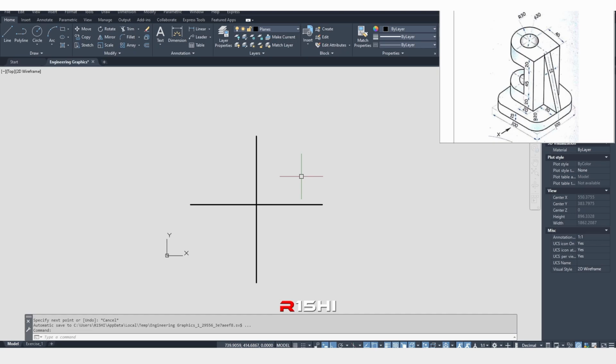In this case, I will draw the front view. We are going to draw the front view, then the top view, and then the left hand side view. And we are going to draw this in third angle projection. So my front view will be over here, left hand side view will be over here, top view will be over here. Just in case I have to get the projections from the top view to this quadrant, I will be drawing the angle line.